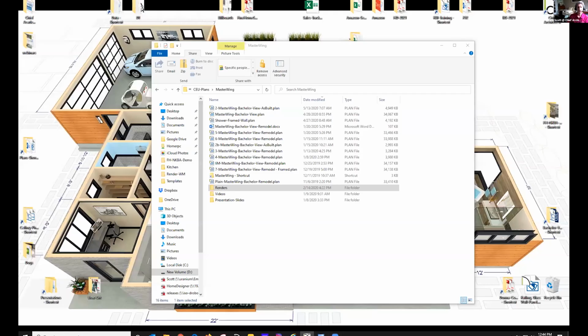Yes, Scott, when you were showing the person who was asking about the construction documents how to show new versus old walls, you could just use that demo wall style instead, and that way that wall is still shown there. And I guess you could turn that off and on depending on how clean you want your documents to be. You could, sure. If you look at what I've done here, this is the remodel project that's fully completed. And when I turn on the superimpose, this wall that was the demo wall kind of went all the way through here.